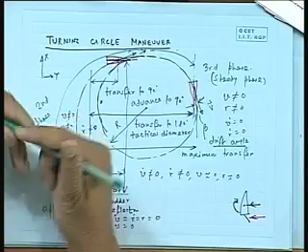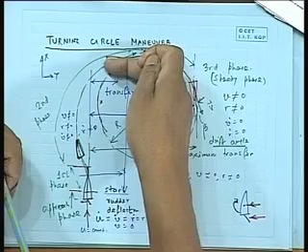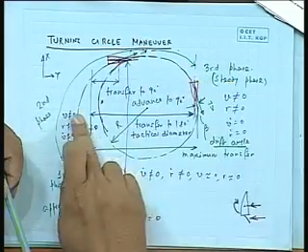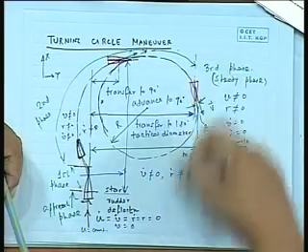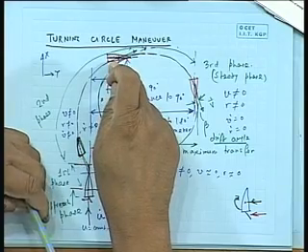So there are 2 points to note. One is where the heading has changed 90 degrees, one where the heading has changed 180 degrees. So at 90 degree heading angle, you have transfer at 90 degrees, and advance at 90 degrees. At 180 degree heading angle, you don't call it advance anymore, because advance is lower. Here you need to know the advance, because you need to know how much it has gone ahead before it turned. Suppose there is a wall there, you are turning, you need to know whether it can actually turn before hitting the wall. So you need to know the advance. Suppose there is something there, you have to turn, you execute here, you need to know how much it has gone maximum. So the maximum is not measured actually, instead of that you normally measure this 90 degree heading angle.